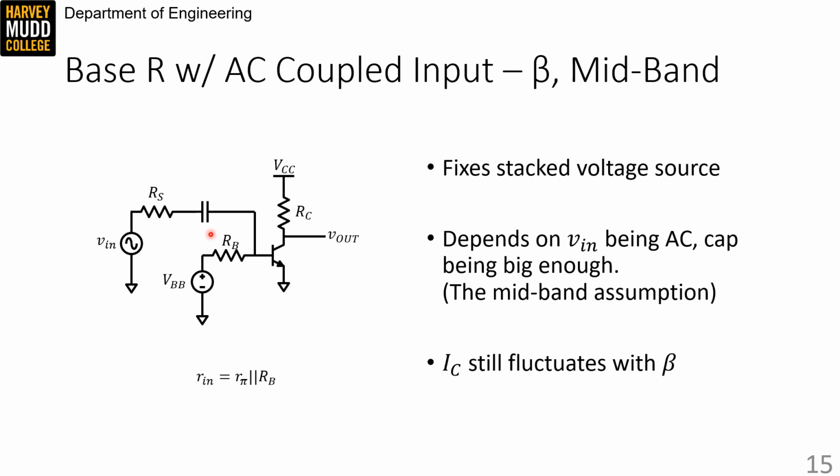Using a series capacitor like this is AC coupling, and it depends on our input frequency being high enough that the capacitor has a small impedance compared to everything else in the circuit. But the input frequency also has to be low enough that hidden parasitic capacitors don't start causing our circuit's behavior to change.